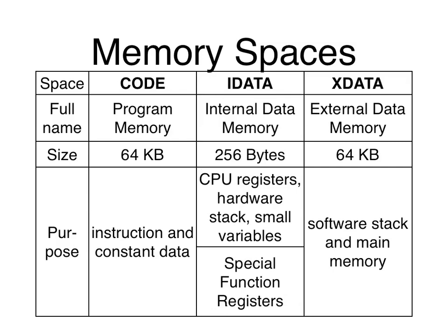Every microcontroller for embedded application has some kind of SFRs. They might be in similar form like this or might be memory mapped, but they are still SFRs, or special function registers. SFRs cause things to happen. They cause you to turn on a light, turn off a light, send a byte on the serial port, or receive something. These are all done through SFRs. So remember, SFR for special function registers.